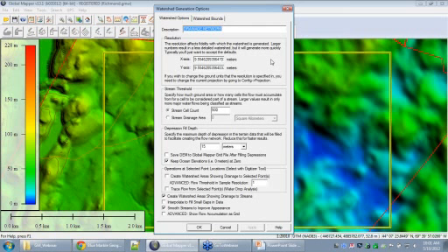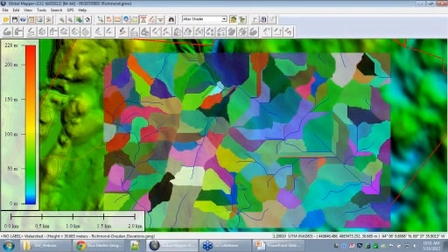Some of those various options, again, the resolution of the drainage network that we're going to analyze. If you're doing a very large area, you're probably going to want to pump that up to a larger pixel resolution, that is, a higher value for your resolution. There's various depths that we can control in here, the depressions that we're going to fill in as those streams form and they flow along. And again, a whole lot of very complicated things that we can add in. Whether or not we're going to trace the flow from a selected point, which is a water drop analysis, so I basically flow from a particular point into those streams and water bodies that are going to form.